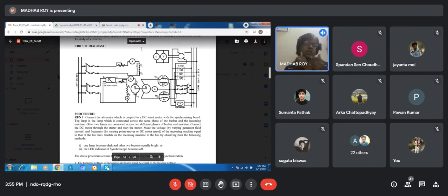So if we increase the power from any synchronous generator or motor, then delta must change. Delta is basically the angle between the rotor poles and the three-phase stator poles. These poles are matched, with an equal number of poles. The construction of the stator of the synchronous machine is the same as the induction machine stator. That means when the three-phase stator carries current, there will be a rotating magnetic field, and its number of poles will be equal to the number of rotor poles.